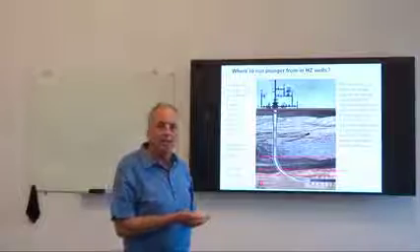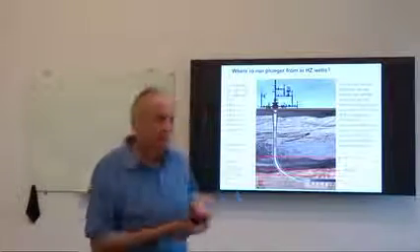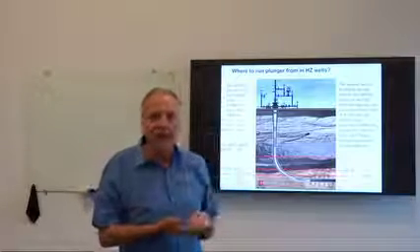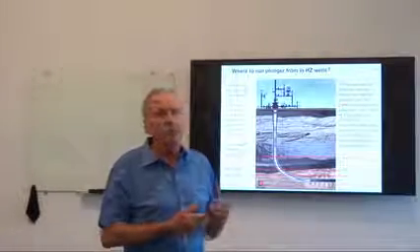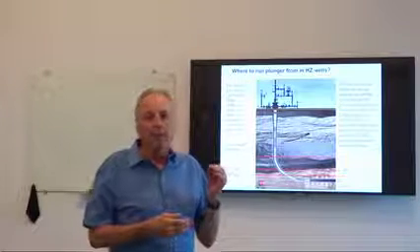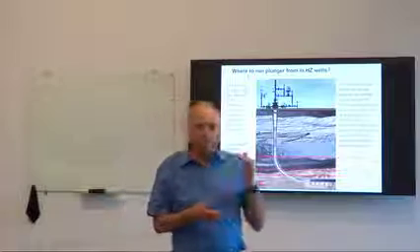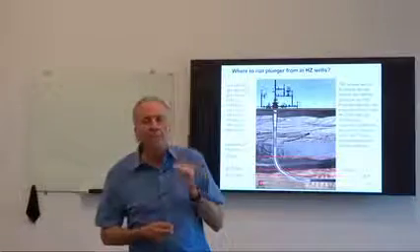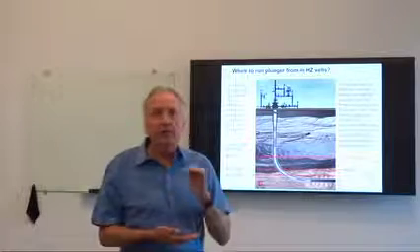We did a study with a customer a few years ago, and we tested various depths. They had actually very deep set tubing, their plunger lift was struggling, and we ran tests on about 30 wells, and in some of the initial wells we were setting tubing at about 50% into the perfs.